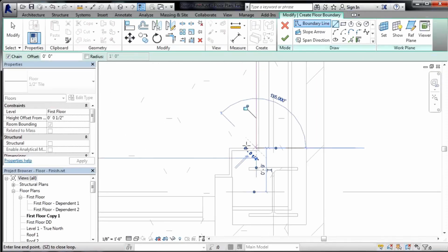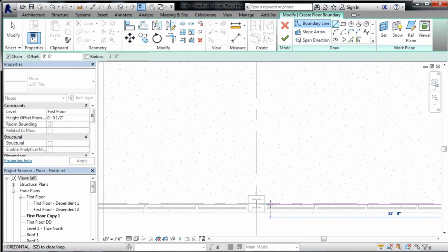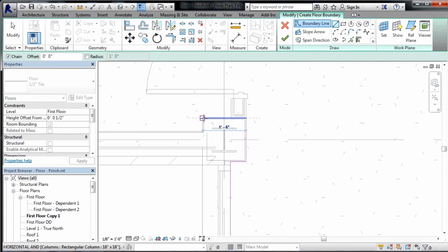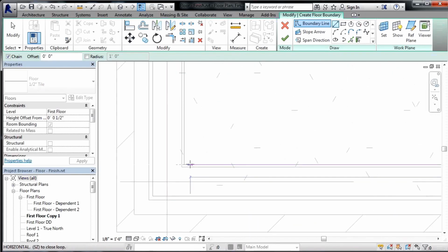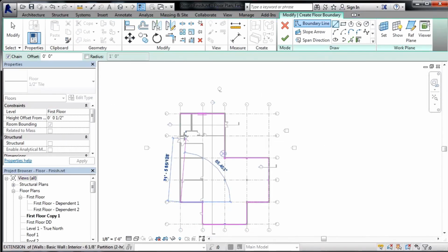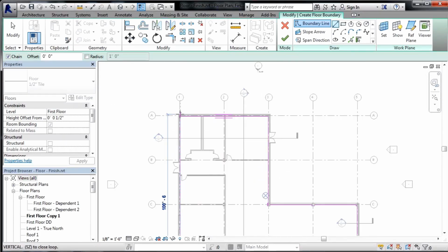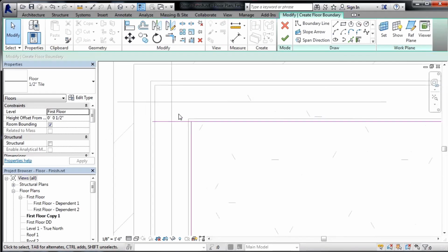We'll eventually come up to the big green check mark in order to finish off the floor that we were drawing around the building. There are certain locations where you may decide to go through doorways instead of just going right through where wall locations are at, and that's okay. For this example, we're not going to be cutting sections through certain parts of the building, and because of that, I'd have no problem in actually taking our flooring material through some of these wall locations.